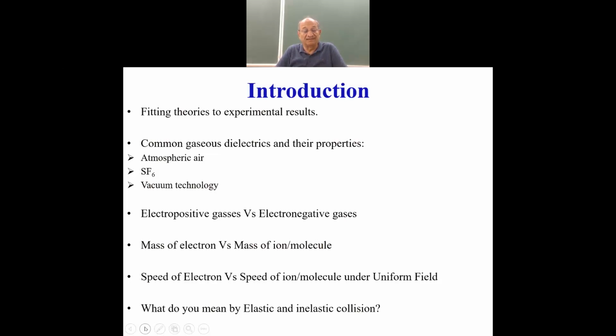That means with atmospheric air behaving like a dielectric. The advent of other insulating gases did come, but it was something like more than half a century ago, that SF6 gas, that is sulfur hexafluoride, an electronegative gas, was identified to be one of the most suitable compressed gases for electrical insulation. Vacuum technology is there since long, but it has its own limitations. The use of vacuum technology in power system apparatus has increased, but not to the extent of SF6 gas application.